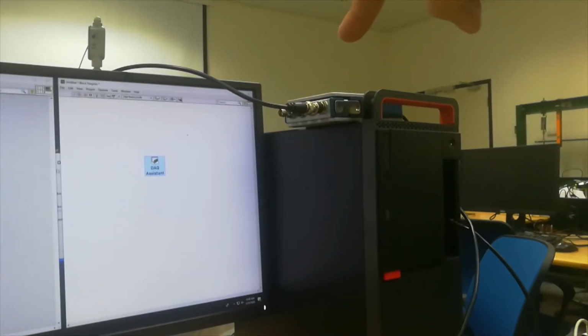However, you will find that the sensor of this data acquisition card is different. The sensor for measuring the pressure is different from the accelerometer sensor of the vibration experiments. Okay? So what I'm going to do now, I'm going to measure the pressure voltage using the voltmeter, and also I'm going to measure the voltage using the data acquisition card. So I will have two sources for the measurements.